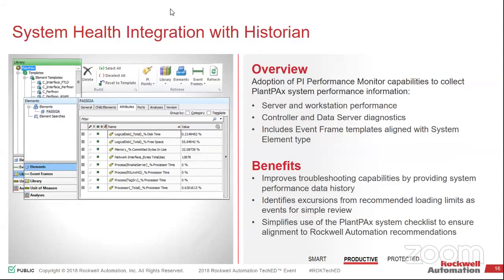So any changes that you make to the top end side propagate to all of the children inside of it, meaning your scan times, the parameters that you would set. It makes it a lot easier to be able to do bulk configuration changes. So all of that is now part of it. And on top of it, it now creates models. So when we start looking at that in Vantage Point, you're now able to see those models kind of getting pre-built for you without you having to do a lot of legwork for it.